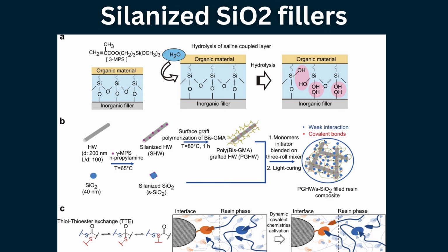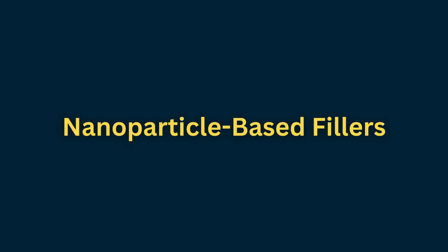Porous sintered silica nanoparticles, produced at high temperatures of 1300 degrees C, possess surface porosity that promotes micromechanical interlocking within the cured adhesive matrix. However, silica alone does not provide sufficient radiopacity. Therefore, mixed fillers such as barium oxide-silica or ytterbium oxide-silica are often used.